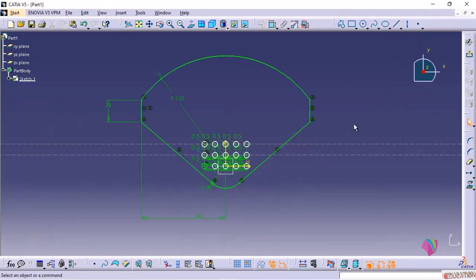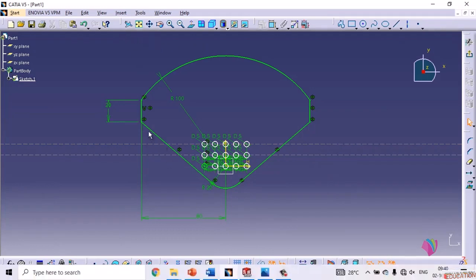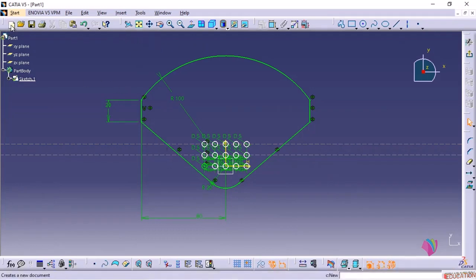In Solidworks, we have seen how to hide and unhide. There are few reference lines that have been formed while we have formed the array or the pattern. We can hide this. We have to find the hide and show icon. So you can just move over to the left top corner and from there we can have a look. These are all file saving and related options. And here these are the view toolbar, and the hide and show will mostly be there in the view toolbar. So here if you move along this direction, here you can find this hide and show. You can see. So if you click here, this gets activated and you can select.